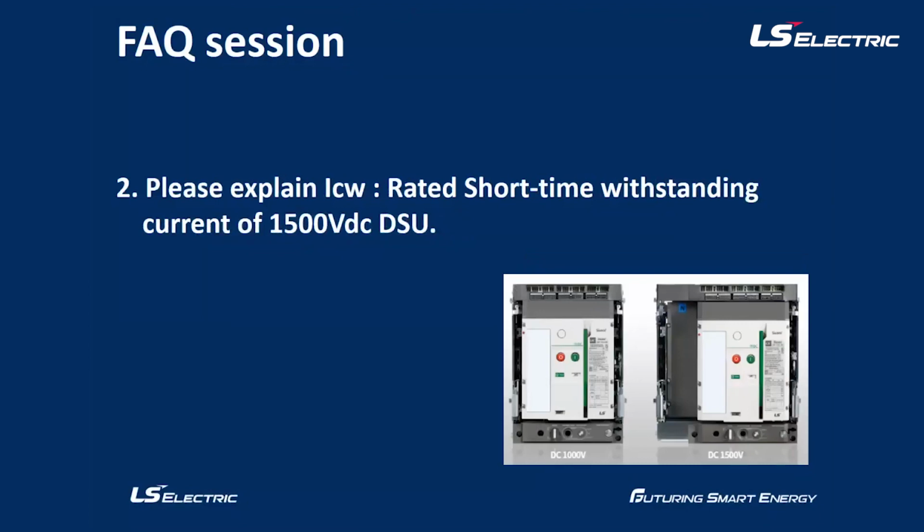Actually, I'm going to start with the ICW, rated short-time withstand current, which is a notion in IEC 60947-1, actually the dash one. It is about the withstanding capability during a short time when current occurs inside the branch circuit.